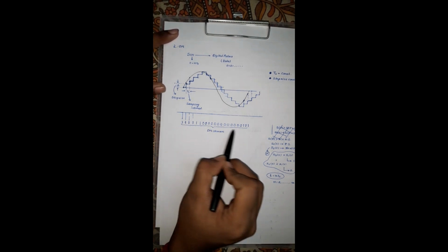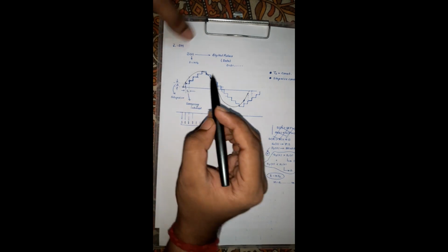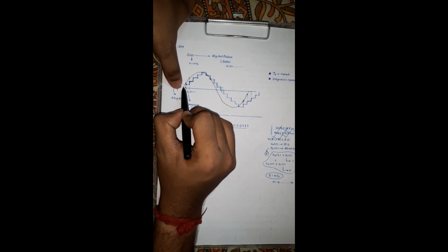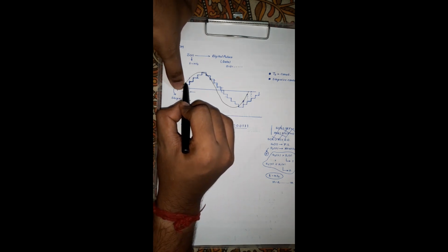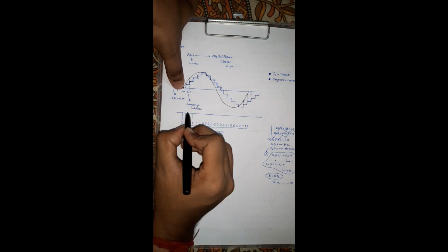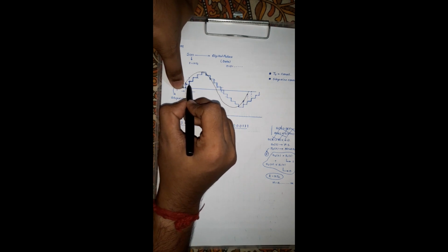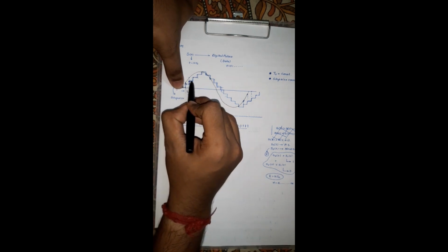What is this signal? This signal is nothing but the representation of this code. What is the circuit actually doing? At the first instant, suppose it assumes a 1. Now at the second instant it checks the amplitude of this black signal. If the amplitude of the black signal is greater than the previous amplitude, then it produces a 1, and when this 1 is produced, a rising step is produced over here. Whenever a 1 is produced again, a step is produced.